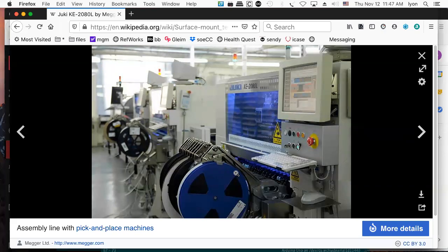And so when you look at the shields that we created for the DSP work, the audio shields, there's a single SOIC-8 small outline integrated circuit with 8 pins that's the heart of the board. It is the MCP4921 Microchip digital to analog converter. The DAC essentially is a surface mount device, along with a couple of capacitors and that sort of thing.